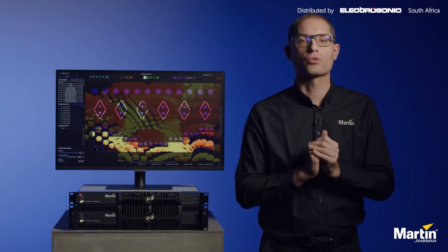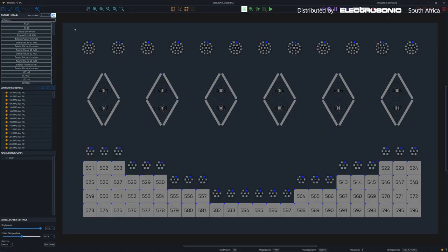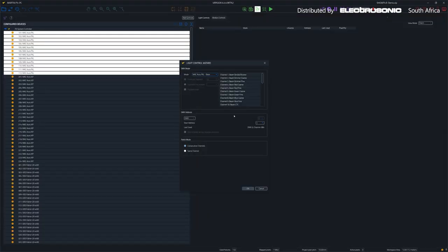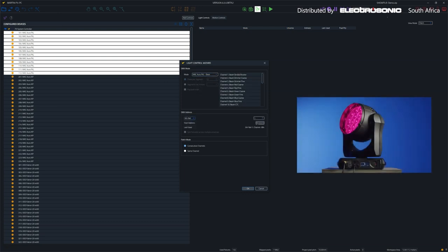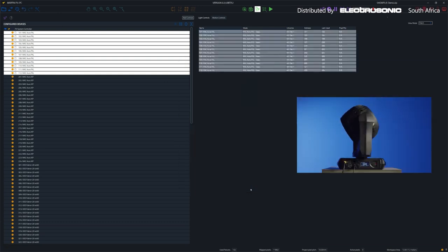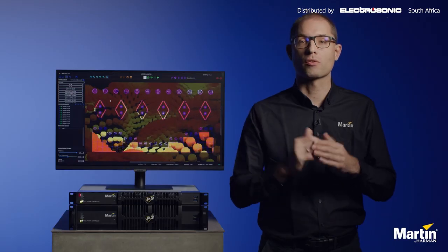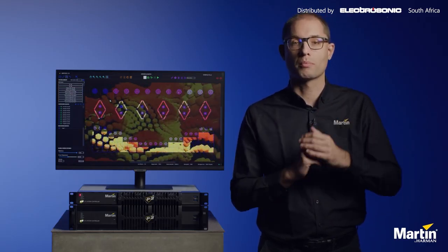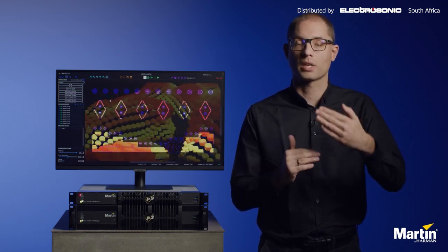If you also want to control the fixtures from a lighting console, you can easily patch them via the P3 system controller. Simply select the DMX mode and start address and the patch is done. No need to walk up to the fixtures and do anything locally via the display. Many fixtures also enable you to freely create pixels or segments to be controlled from the lighting desk, or even invert the pixel order for fixtures hanging upside down.